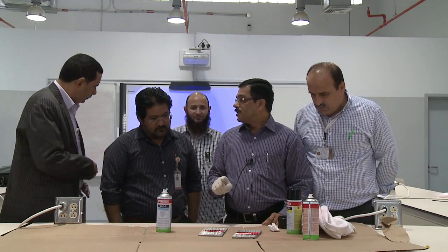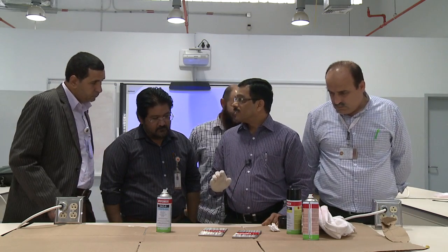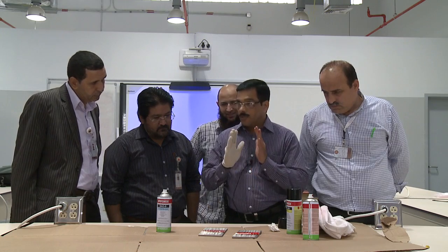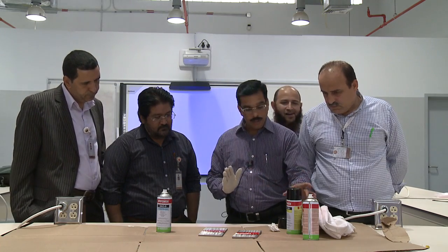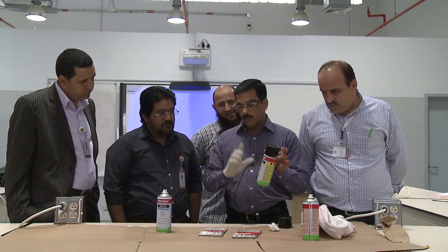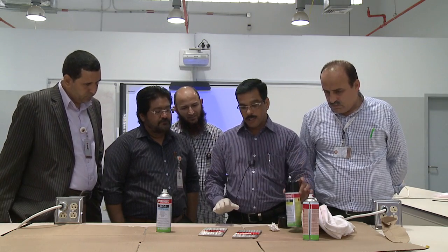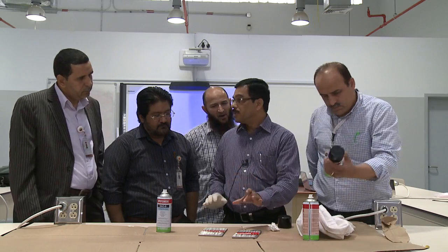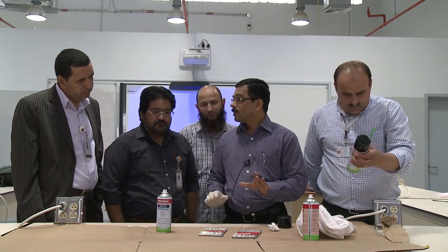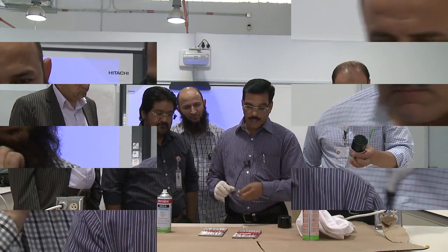Next step is the dwell time, what we told. So how much dwell time? Usually we give 10 minutes as per our manufacturer recommendation or as per the procedure. We are following the manufacturer recommendation, we have to give 10 minutes dwell time. So just wait for the 10 minutes. Okay.